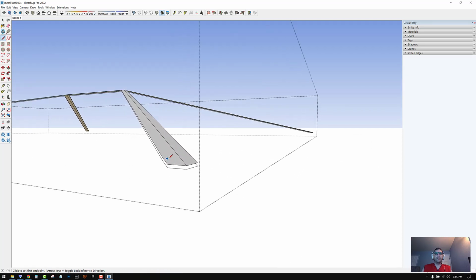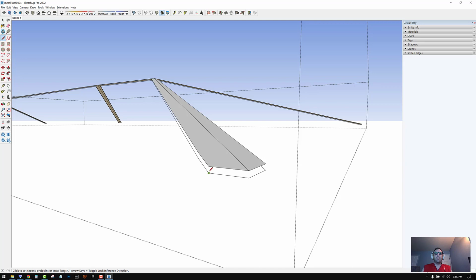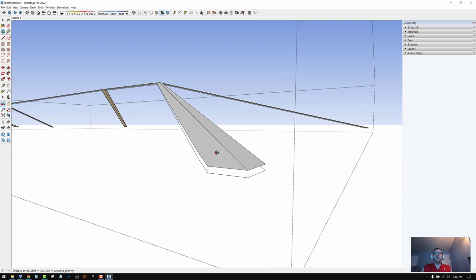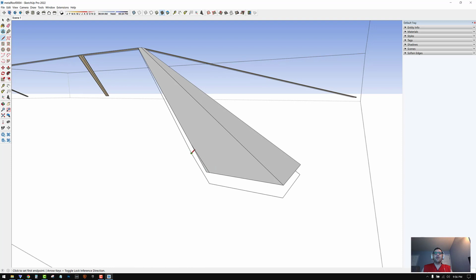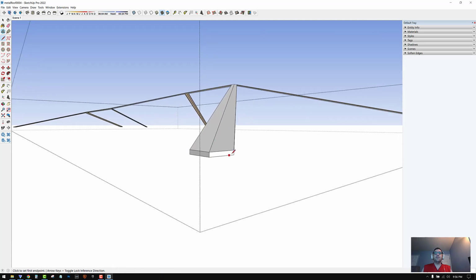Did something, yeah, I didn't have that line straight. See, if you know you messed up when you make all the outlines and the face doesn't create, you know something's wrong. So if I hold down Shift, I can straighten out these lines without having to go back and redo it. I can just fix it like this. Now if I delete the crooked lines and then keep the straight ones, it should work. And it did.